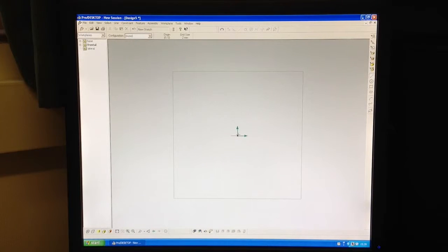For some reason the path tool works most effectively if the initial line from which the profile is moving is at 90 degrees, and the easiest way to do this is to press shift on the keyboard, keeps everything straight, and I'm going to come up by 80mm. I'm going to go across by another 150 and then back down again. You can see a sort of handle shape appearing, like so.